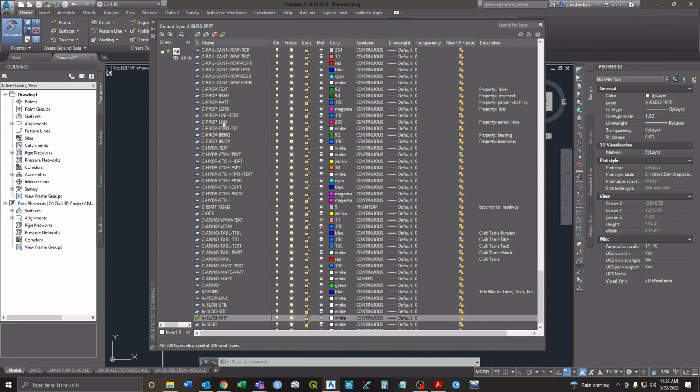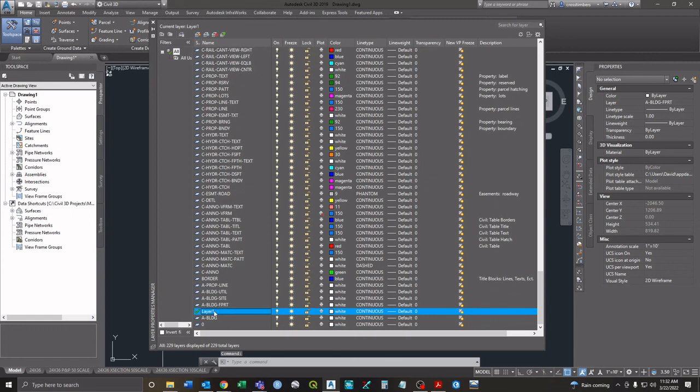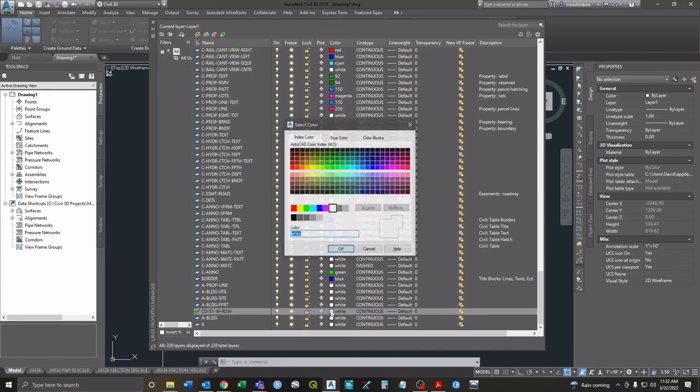And so again, if you're in the layer properties, you go up to this little orange ball one, and it's a new layer. And so you can create it, and what I would do is say, all right, it's cross drain 1, and then say west side of the road right-of-way, something like that. And then you can change it to whatever color you want here.